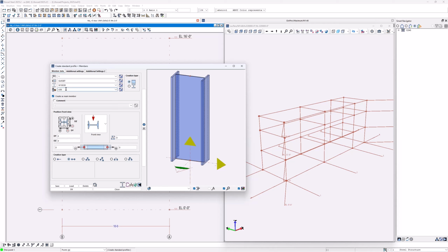And as it comes to steel grade or material, we call it material simply because it could be something else than steel. It could be aluminum, it could be timber, it could be concrete, it could be insulation material. It doesn't really matter. There again as well, if I press on the icon, it will show me anything that starts with A36 simply because I already entered A36. It works a bit like a filter.